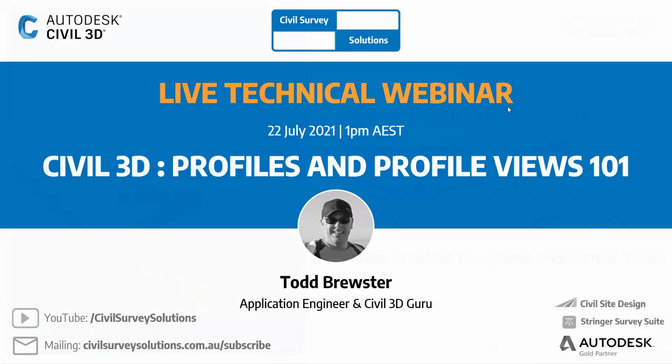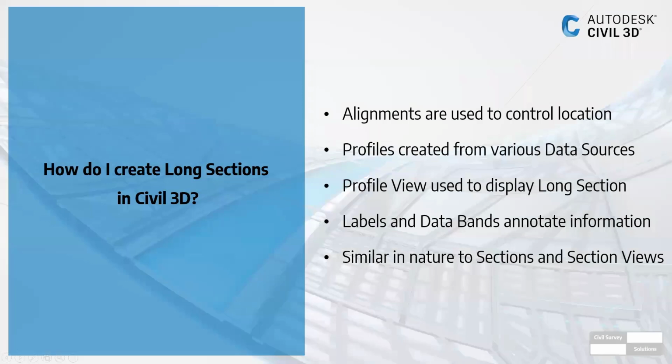So what is a long section? How do I make them in Civil 3D? Long sections are known in Civil 3D as profiles and profile views. And just like what everybody would be familiar with, the alignment is used as kind of the placeholder. It's the parent, so to speak. It controls a location in plan, and it is the placeholder that everything is attached to.